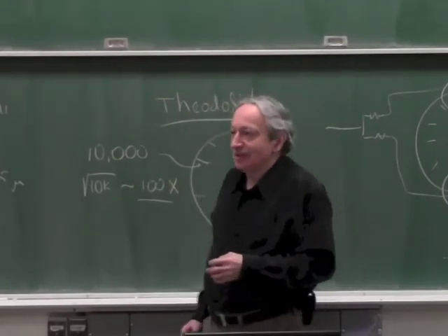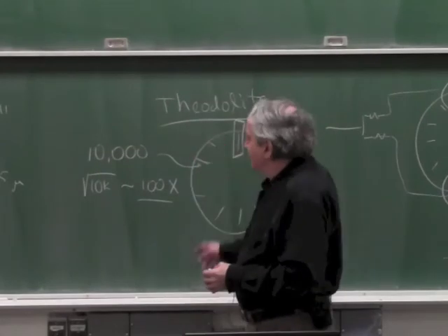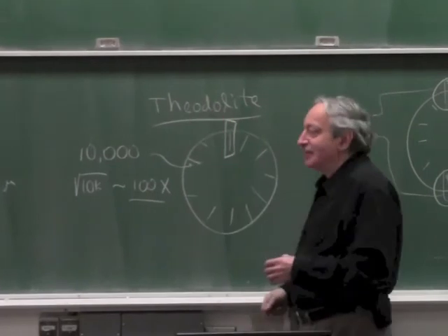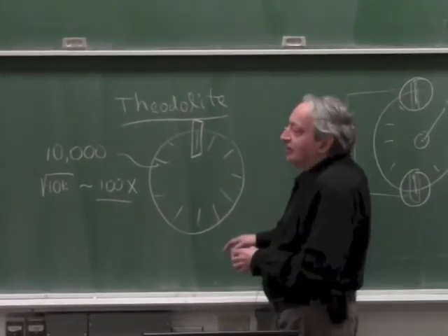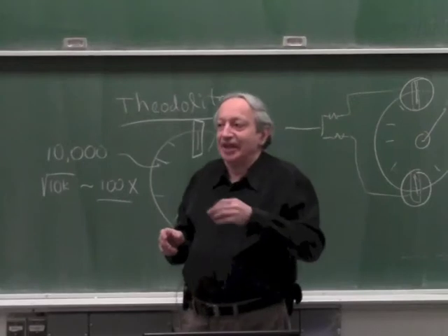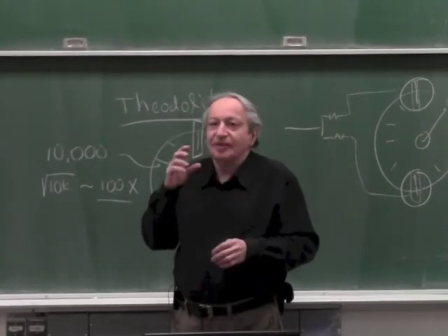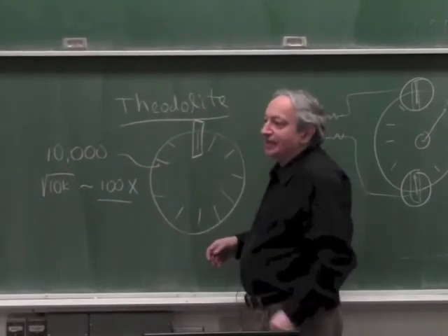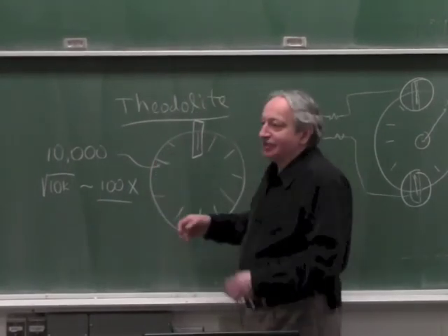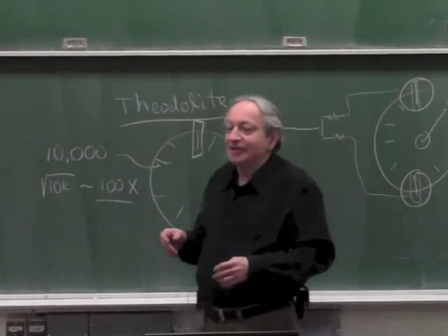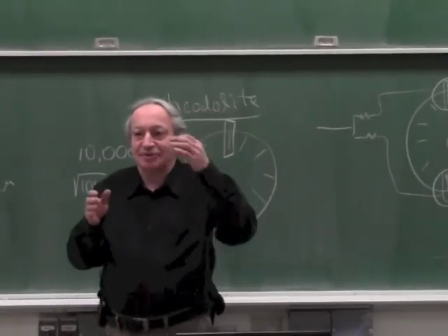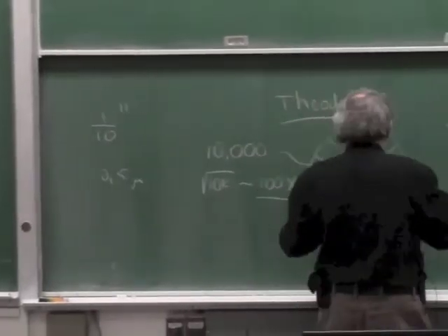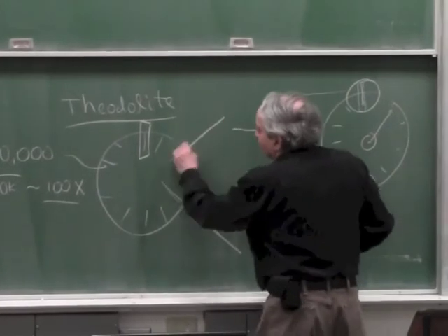And I gave the example of how Ramsden did the first sextant, which is also across the wall here, and it's worth your while to have a look at what it looks like. The way he did it, he took microscopes and aligned them in such a way that at each position of the wheel, the microscope had to stay aligned, and then he corrected the teeth of the gear by filing or by lapping until the microscopes always lined up with the lines. Again, what he did, if this was the wheel, he put microscopes at random positions which aligned.